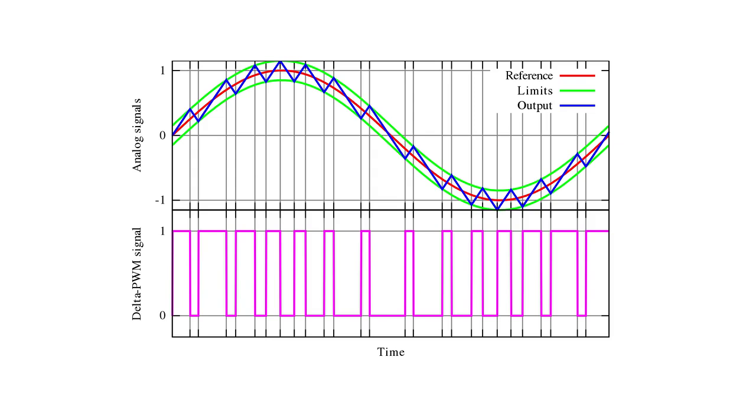So what that does is it allows it to recreate, and I wish I had some better pictures here, but at the end of it, you take that pulse width modulated signal and you filter it to get rid of all the trash, all the switching signal, everything above the desired frequencies. So when you look at it with the proper filtering, it is actually reproducing what you put in. Although you put in an analog signal and you're getting more or less a digital signal out, you're trimming off the digital part of it, the higher frequencies that it's switched at.